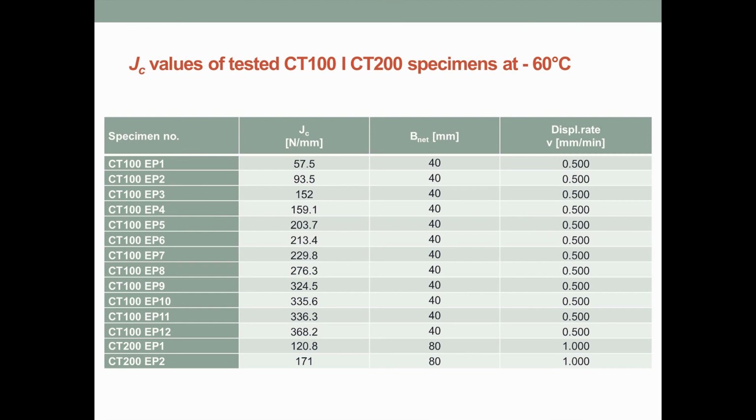In order to verify the obtained prediction curves and to get better insight into the results, we performed testing of 12 CT100 and 2 CT200 specimens at the same temperature as CT50 specimens, in accordance with appropriate standards which we have mentioned before, and the obtained results of the testing are shown here in table 4.